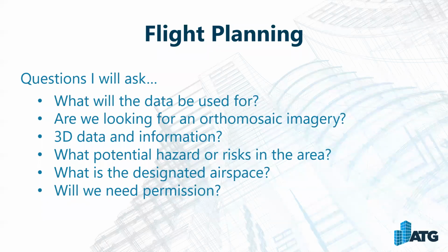So first things first, when I go to think about planning out a site, I'll ask myself a handful of questions. What will the data be used for, whether we're just using it for inspection purposes, or if we're looking to do site plan grading out of it, things like that. Are we looking for ortho mosaic imagery? Again, 3D data. What are the potential hazards or risks in the area? What's the designated airspace? And will we need permission to be able to fly?